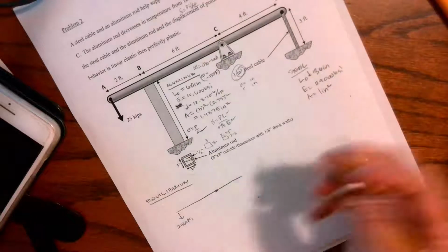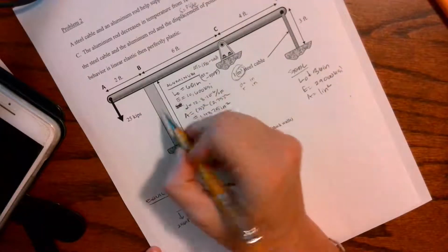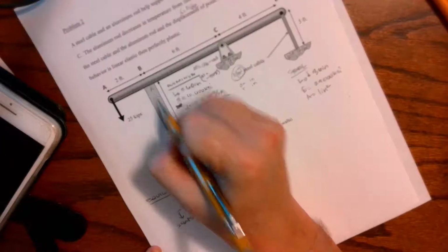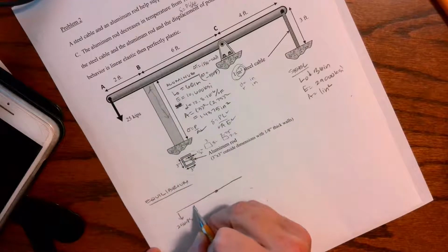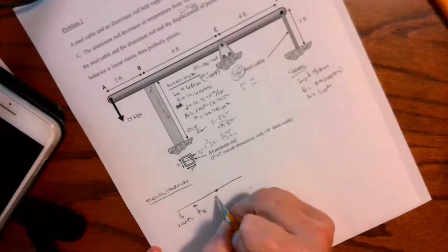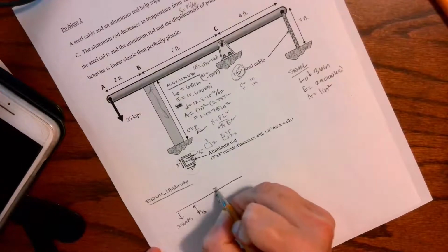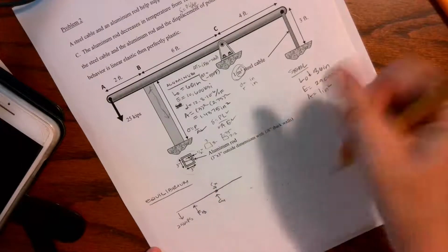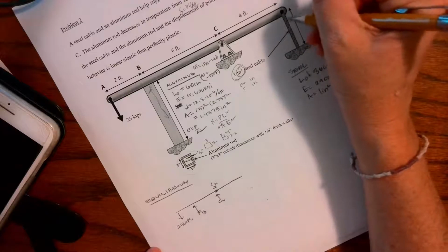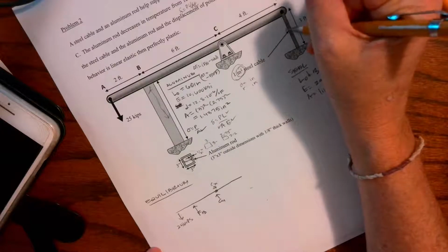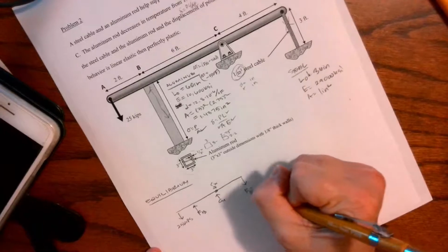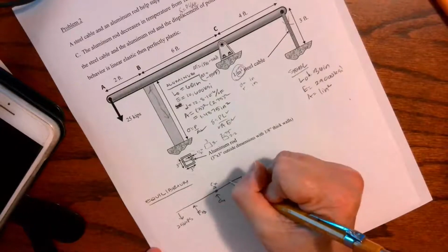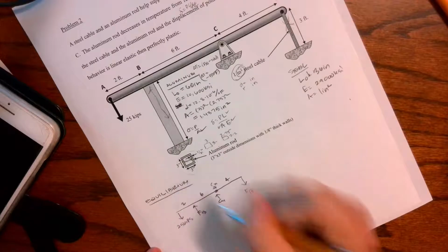And I'm just going to go ahead and assume that as I'm going through. So if this is a compression member, it is pushing back up. A compression is pushing down on the member, pushing back up on the joint. So I have a force at B. I have CY and CX. Don't forget about those. If this is a tension member, we're trying to pull up. This member is being stretched up. So we're pulling back down on the member, and I have that force at D. I have 4, 6, 2.